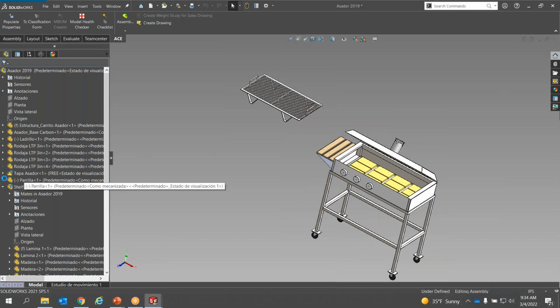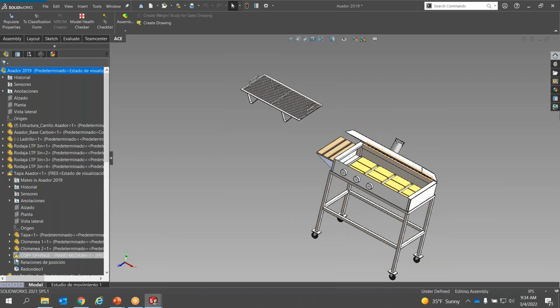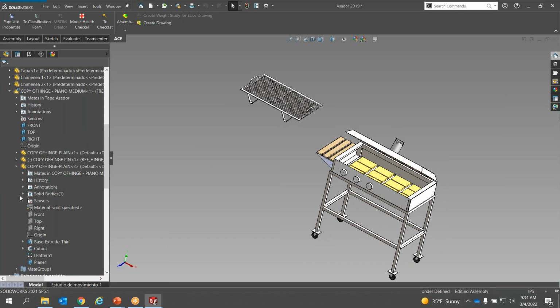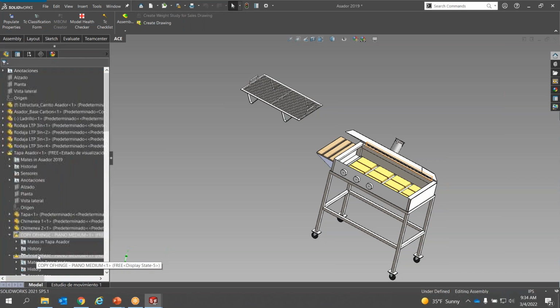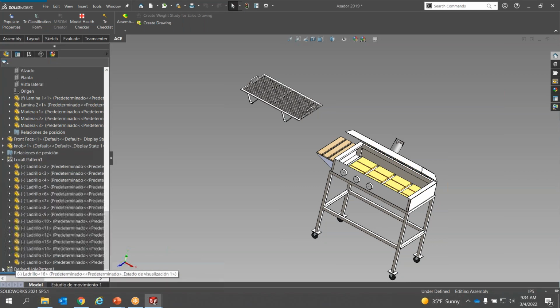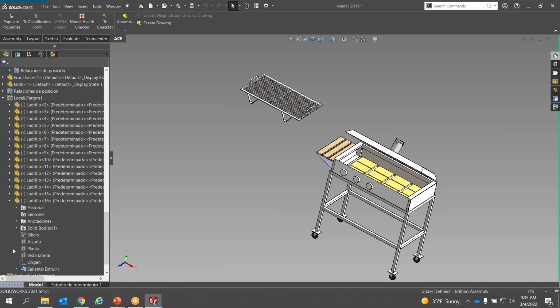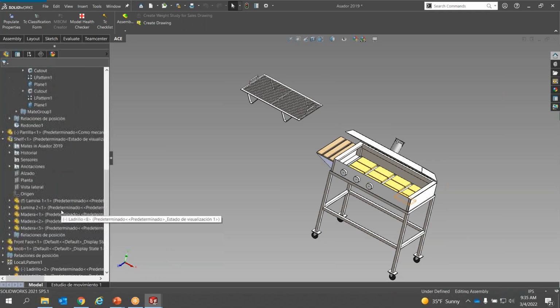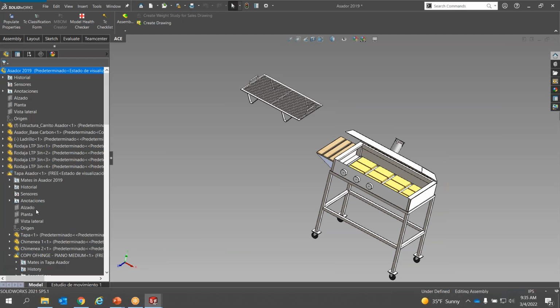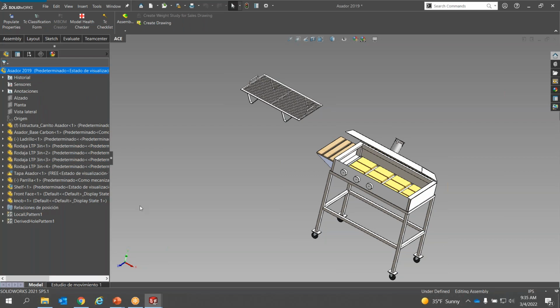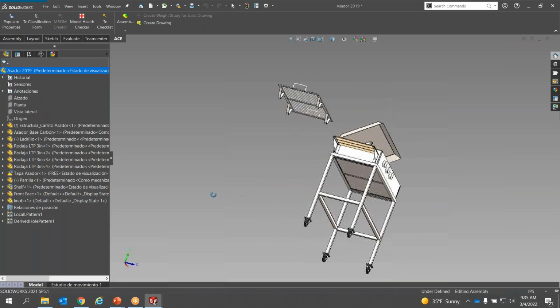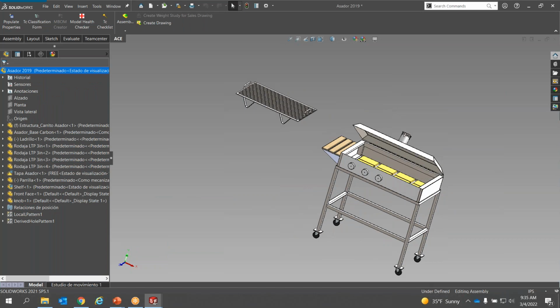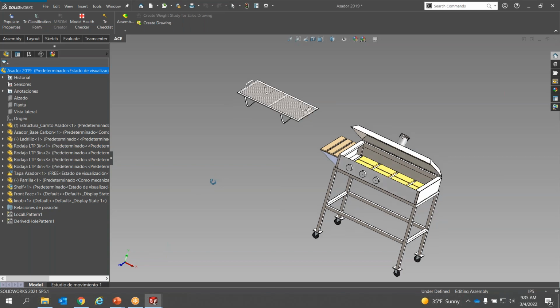Let's say I want to look through this thing and I'm going to scroll down through this part here. I'm going to go through this hinge and find something in the annotations and open everything up. But now I've got to go through to the very top. Or I want to go down through one of these pieces and keep looking through, and I find everything I need. Well, everything's expanded out now. I don't want to see that. Shift C collapses it all. So it makes you a little bit more efficient, a little bit more effective in doing your tasks.